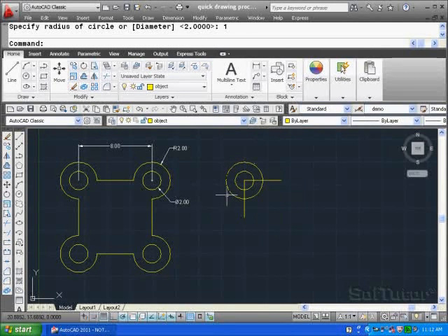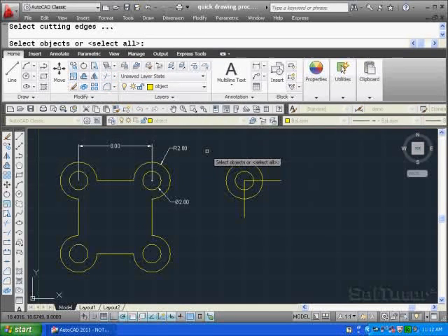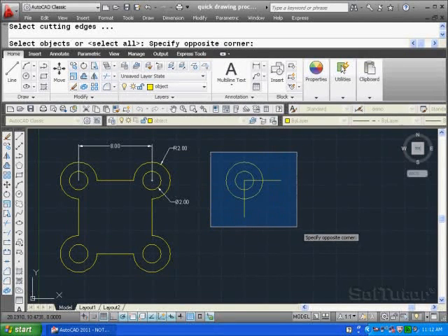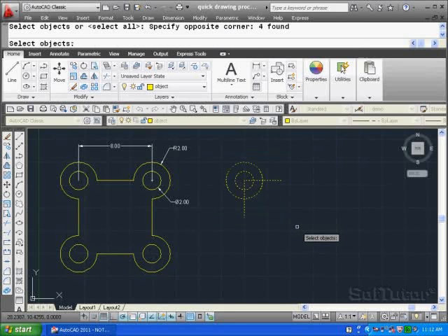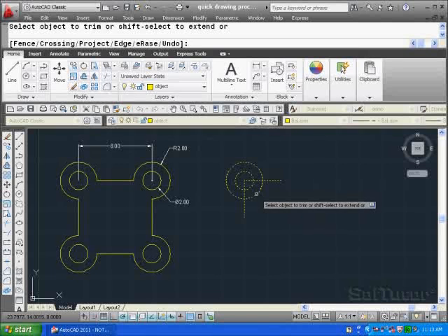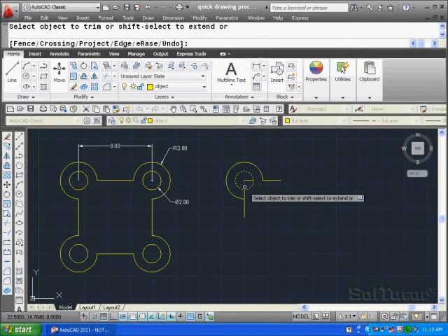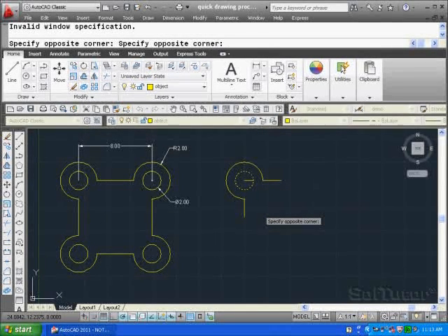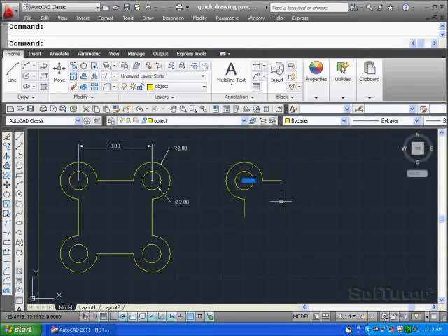Now I want to clean this up and replicate it. So let's go up here to the trim command right here, trim, and it says to select all the objects or individual objects. We're going to just select everything. So drag the left mouse button down and click, and then hit the Enter key and take out the pieces you don't want. So I want to remove this section here, and also this here. Oh, there we go. A little mistake there, but that's okay. We'll just take that out. I'm going to hit the Escape key, select that, and remove that right there.